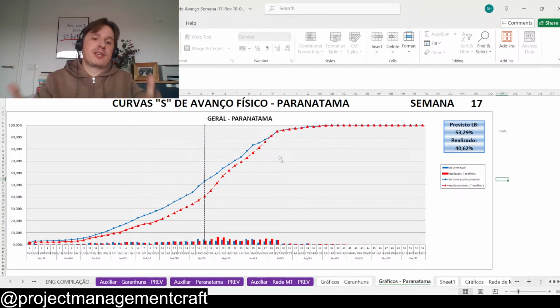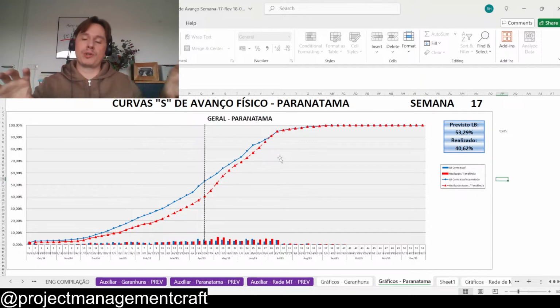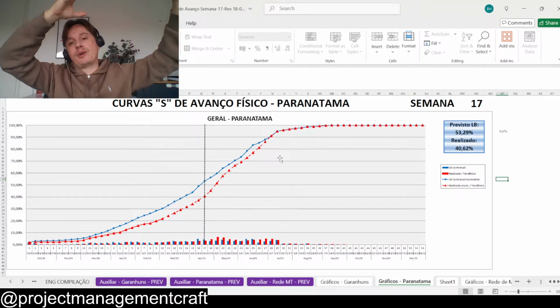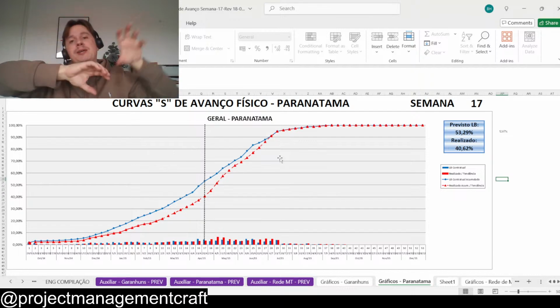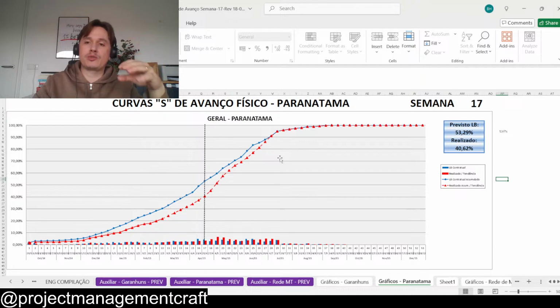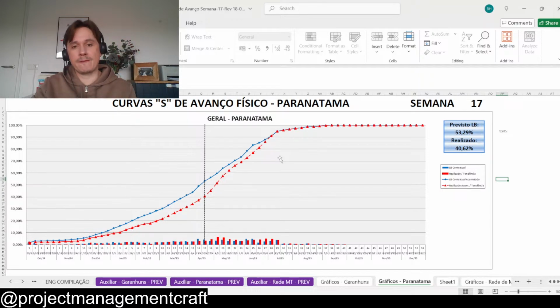That's the interesting part, because with all those S curves from different suppliers that they were working on site, it's possible to consolidate because they come from the same WBS levels that you have there. So the macro levels are all the same, so they're all interconnected. So you can organize this in a very nice way to provide a very high level report, and we provide further breakdowns, even to localize deviations there.